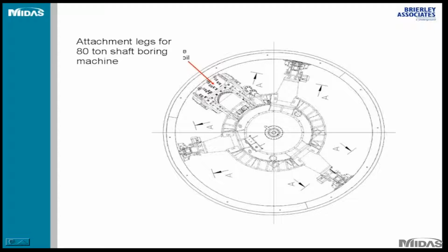Is the as-constructed shaft watertight? It was excellent, and we didn't have anything except very few drips. Between each segment, as I said, each ring has four segments, and there are gaskets to keep water out. There is a special gasket design, which I didn't cover here, to guarantee that under different pressure conditions you wouldn't have any leak.